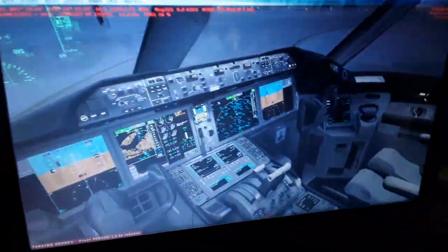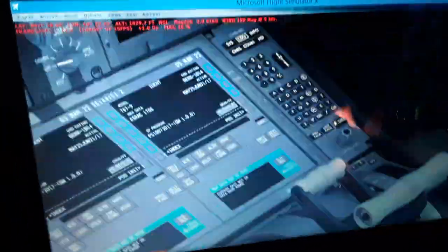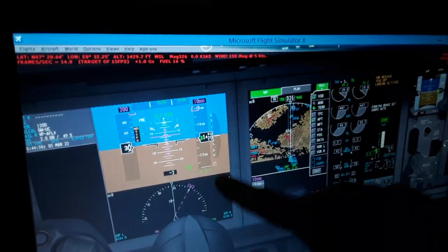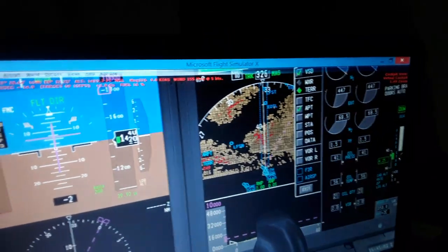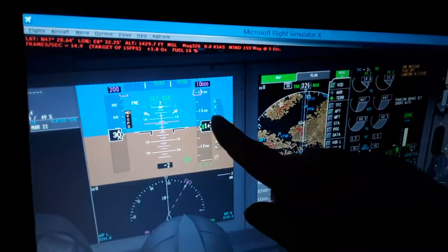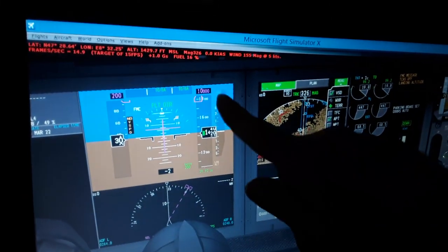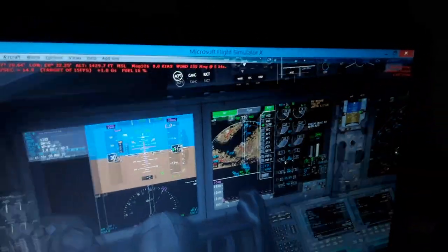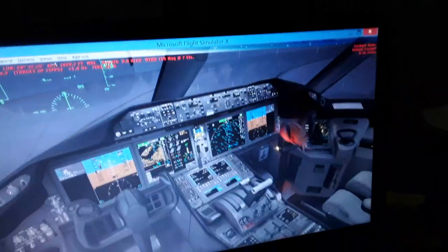So you will see, using the flight management computer later here, we're going to create a flight plan. It's going to be displayed in the primary flight display, as you're going to see over here, in the HSI, and also in the navigation display, the horizontal component, also the vertical component. So you can see the airspeed, the altitude, the vertical rate of climb or descent of the aircraft, the pitch ladder. Here the flight director. So I will talk to you about these instruments.